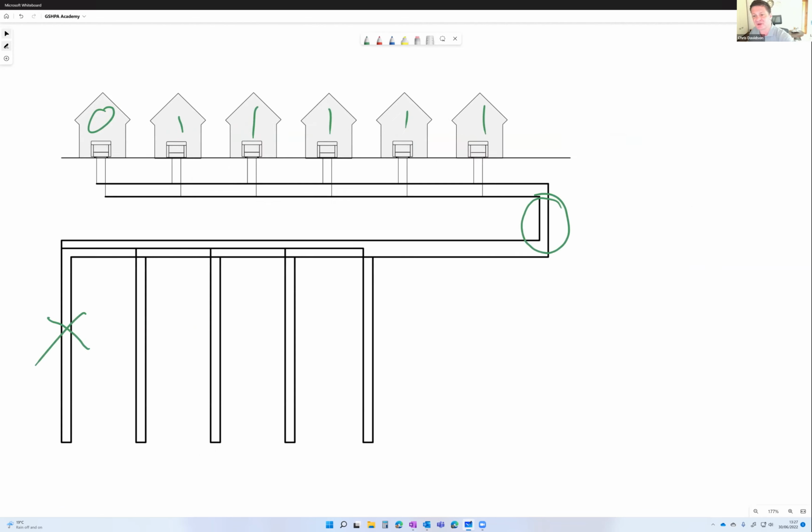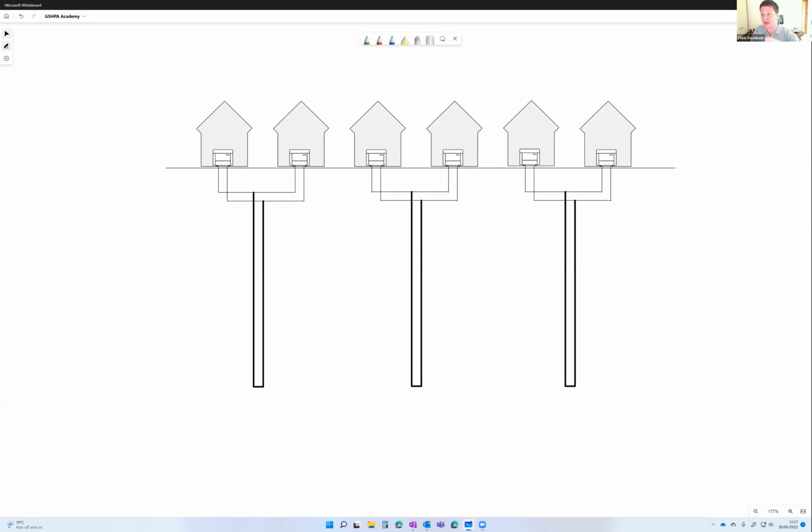So the alternative, at the other extreme, is to break these heat networks up. Here we've got 2 dwellings perhaps connected to a single ground loop. That might mean a bit more ground loop to go in, but it keeps the header pipe sizing right down. In this instance, the header pipe sizes could be smaller than the borehole pipe sizes and still give you an acceptable pressure drop in the system. There's an excellent session hosted by Robin Curtis on pressure drop, which we did a couple of years ago, so it's worthwhile having a look at that.